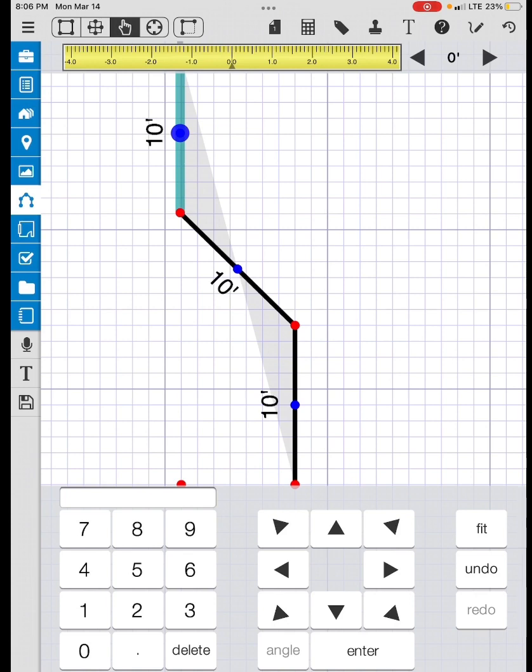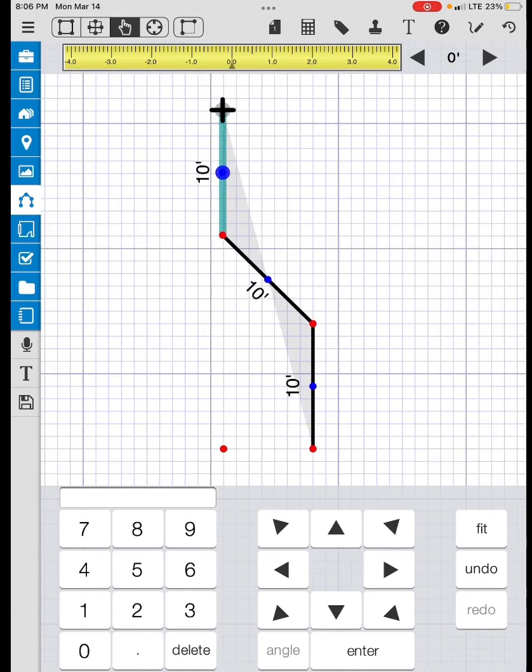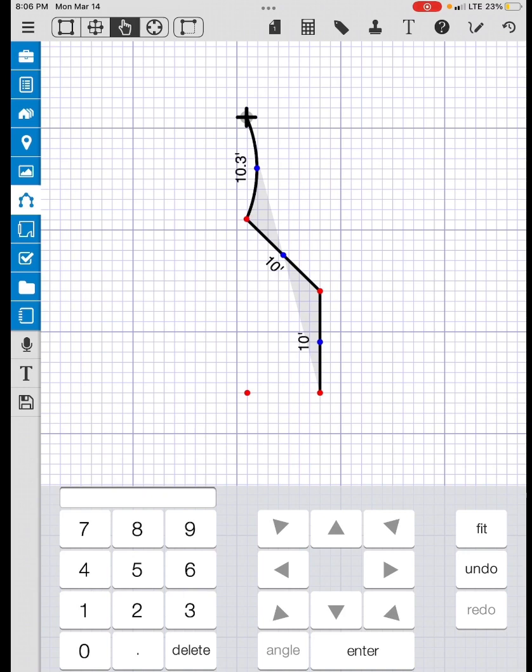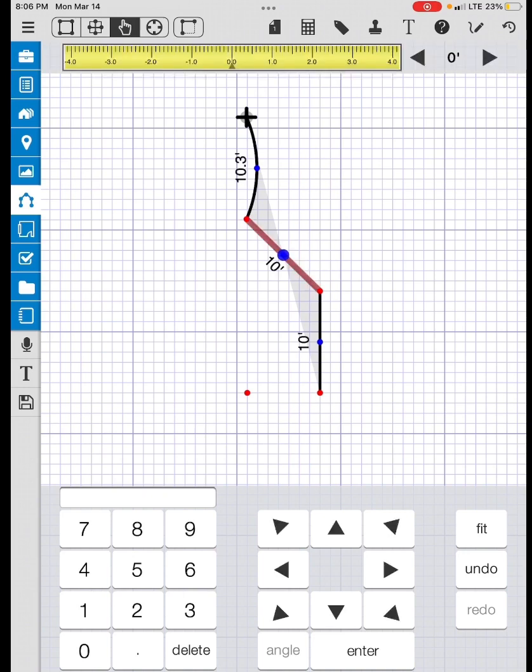So you see, now that we selected that one, there's a ruler that comes up at the top, and there's some arrows on the right. If I start adjusting these arrows, see 0.5, 0.6, 1 inch. So it just curved my line 1 inch. I'm just going to click away. It's going to save it. And so you can curve it by using the pointer finger, selecting the blue dot, and using the arrows, or you can actually press on the ruler with your finger and drag it.